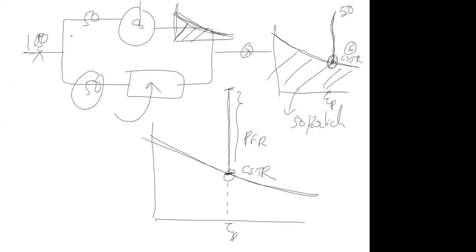Let's take a CSTR. Let's say initially 15 particles came, later 14, later 12, later 10, later 6. That 6 is a special time. Why am I considering it? Because at that time 6 is the number of particles coming from the CSTR. That residence time is tau p. At that residence time you observe suddenly 56 coming, and you will be surprised. Where is this 56 from? The 6 is coming from the CSTR, because you are observing both here, and 50 is coming from the PFR.